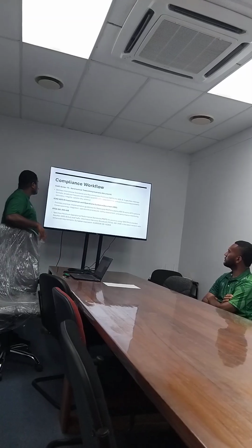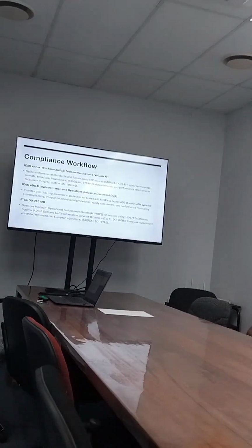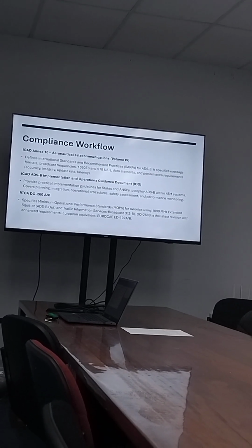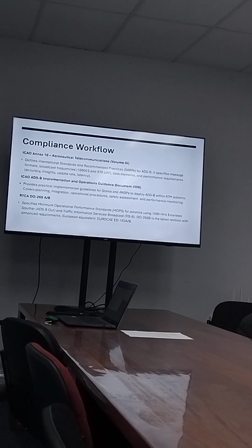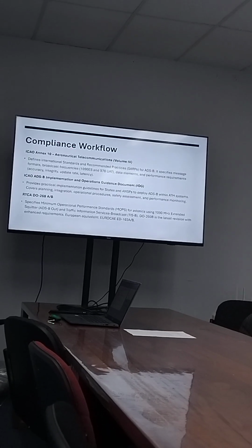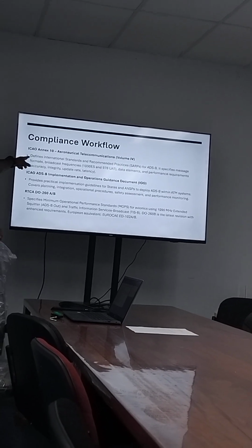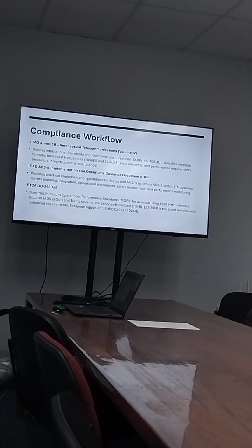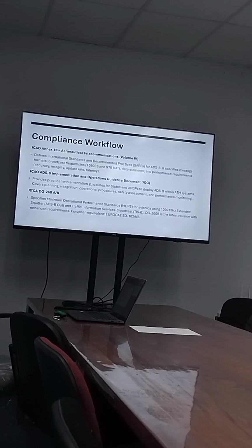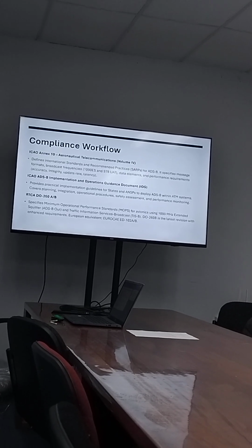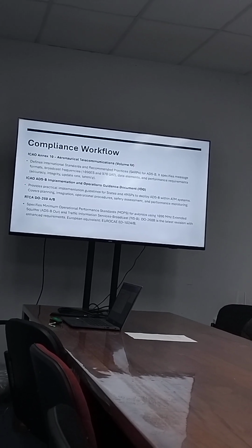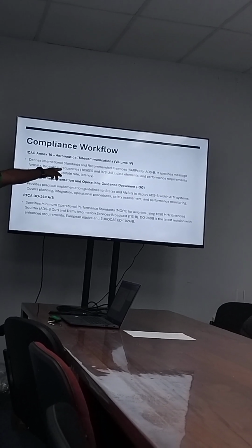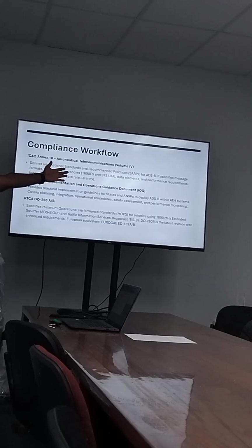Moving on, compliance workflow. Since we work with standard safety, we are governed by ICAO, which comes down to our governing body here in Fiji, which is CAP. And we are governed by the ICAO Annex 10, Volume 4, for ADSB, which defines SARPs, standards and recommended practices for ADSB. It specifies message formats and broadcast frequencies, which is 1090 MHz. 978 is basically for the US.